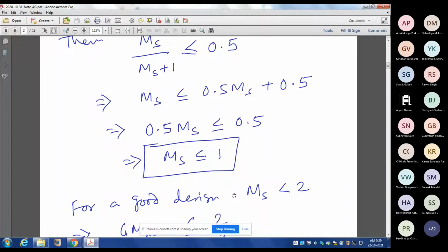Earlier they used to design controllers just based on gain margin and phase margin specifications, but after a lot of study and many failures, they saw that the sensitivity peak Ms is an important measure for robustness. So they consider Ms less than or equal to 2.